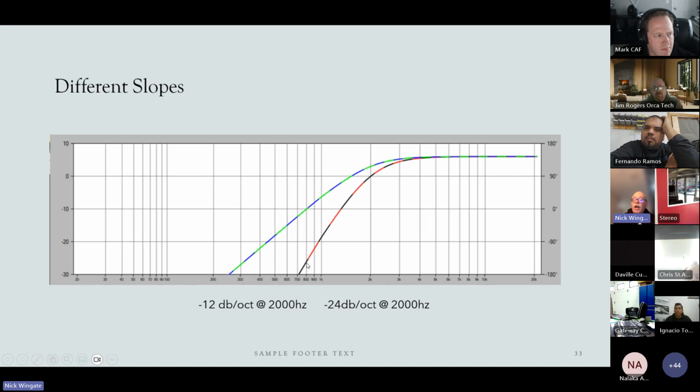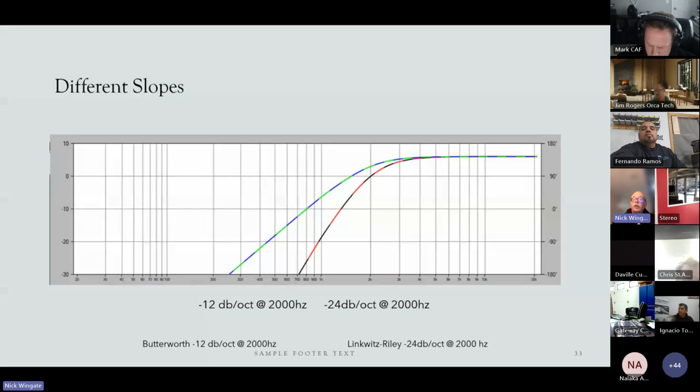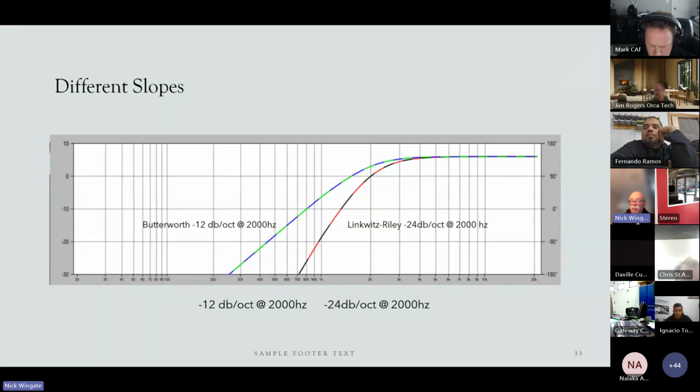So if you have a tweeter that has a higher free air resonance, let's say like 1000 hertz, and you've got a mid-bass driver that doesn't play that high, you're going to need to put a 24 dB per octave slope on the tweeter, and probably maybe a 12 dB or a 24 dB on the mid-bass driver at like 2700 hertz. That's when you gap the crossover. It'll still work, but you need to be careful. This is the reason why you want to choose either a 12 or a 24, depending on the power handling of each speaker.